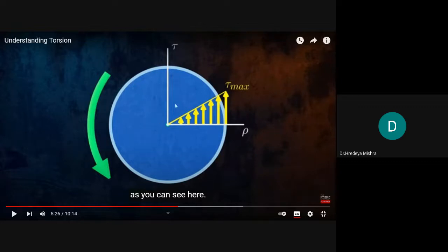Okay, because here there is no stress, we don't need material here. So we can make this solid shaft into a hollow shaft and remove the material. By this action, we can save the material, as well as get a lighter shaft for use.